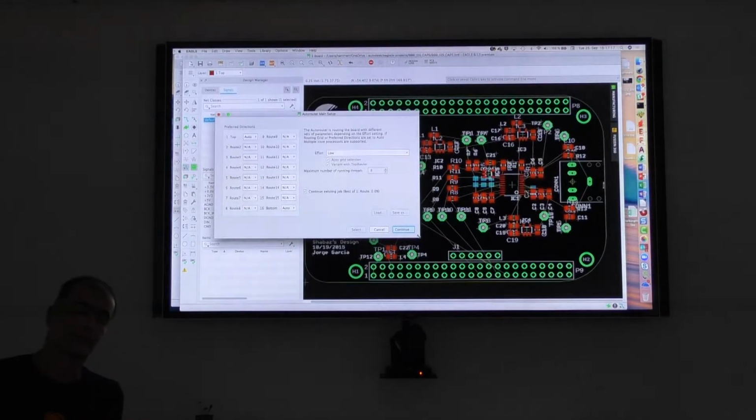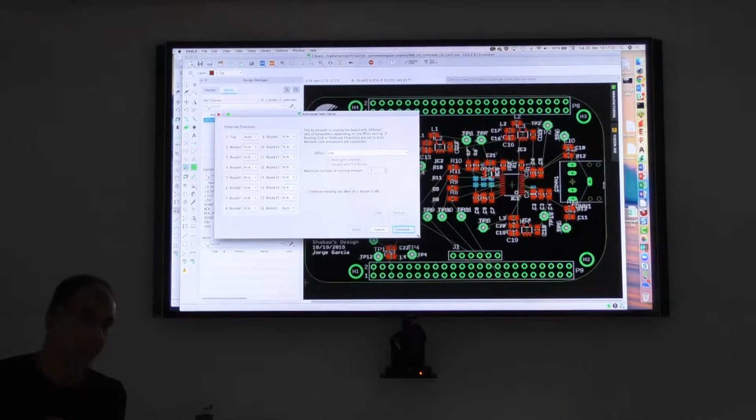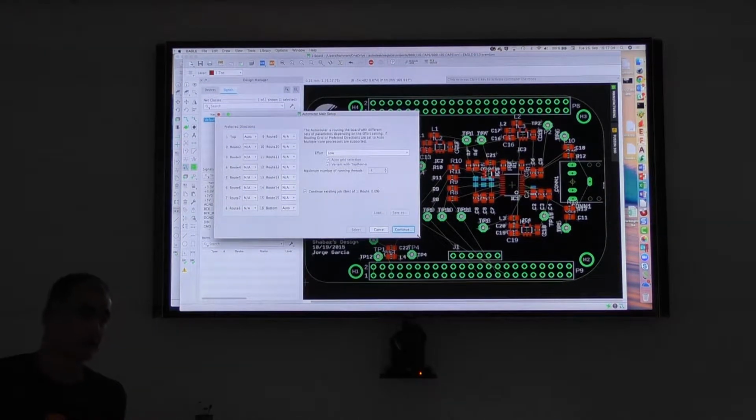You have to think about maybe routing grid, about how many layers the autorouter should use, and you have to set your design rules before you start the autorouter in a way so that you can be sure that it really works. If you have enough time, then the autorouter will finish with 100%, if you don't have any other problems. Of course, if you have constraints or problems in the design rule settings and you get error messages before you start the autorouter, you can be sure that it can't be done by 100%, of course. So that's what Andy said.